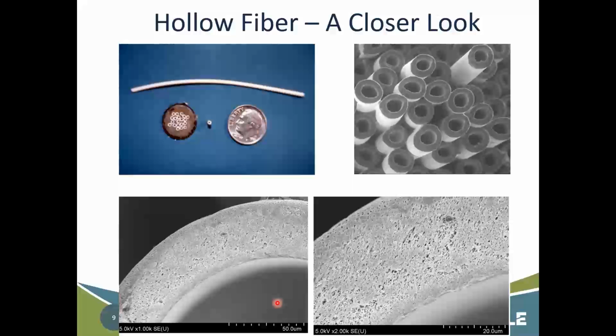And again, it's an engineered membrane, so it's highly uniform, and it's capable of very high and absolute removal of a targeted particle size, just as long as it maintains its integrity. And EPA says that it's well documented that if you have good integrity with your membranes, you should consistently be able to achieve less than or equal to 0.05 NTU.